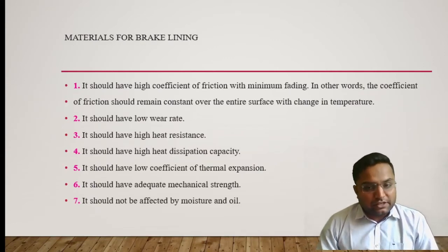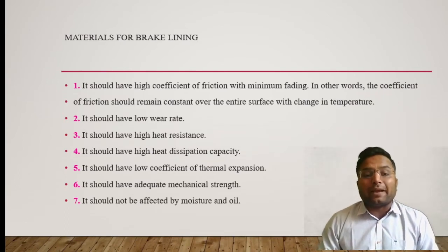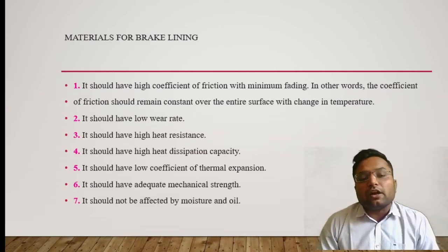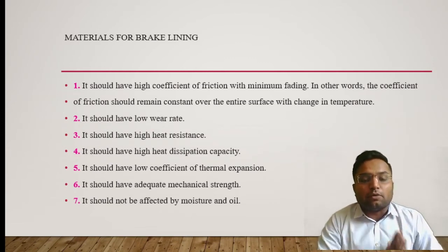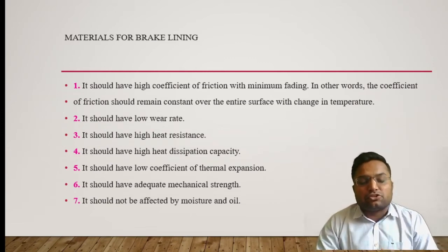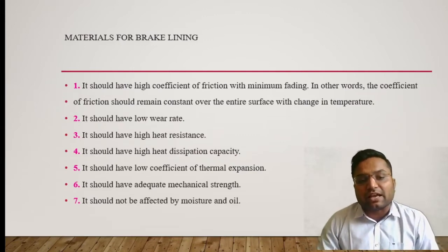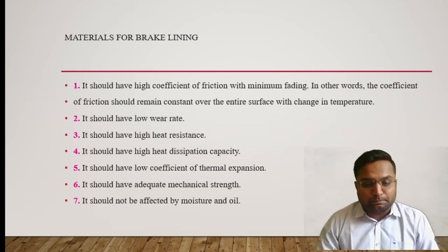At the same time, it shouldn't show any kind of wear according to its working condition and the atmospheric condition. Fourth point, it should have high heat dissipation capacity, because heat is unavoidable in this friction mechanism. Ultimately friction brings heat, and this heat is generated just because of a higher amount of friction. This higher amount of friction will ultimately lead to excessive heat generation, and this heat should be dissipated with the help of natural heat conduction and convection. We have to design our system, or select that material, so that it has high heat dissipation capacity. Clear?